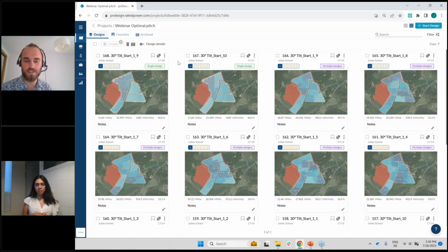If you have that ready, maybe you don't have a performance ratio goal, but you have an LCOE, and you can also find some other comparison values on the internet. So I would go for that one. Then overall, and that's why I mentioned the GCR as well, it's always a good indicator. I remember that in some countries it's compulsory to have 60%, but not more. If you have more than 60% ground coverage ratio, the whole environment and the wildlife on that area is prohibited from growing and being maintained. So I would also go for that ground coverage ratio.